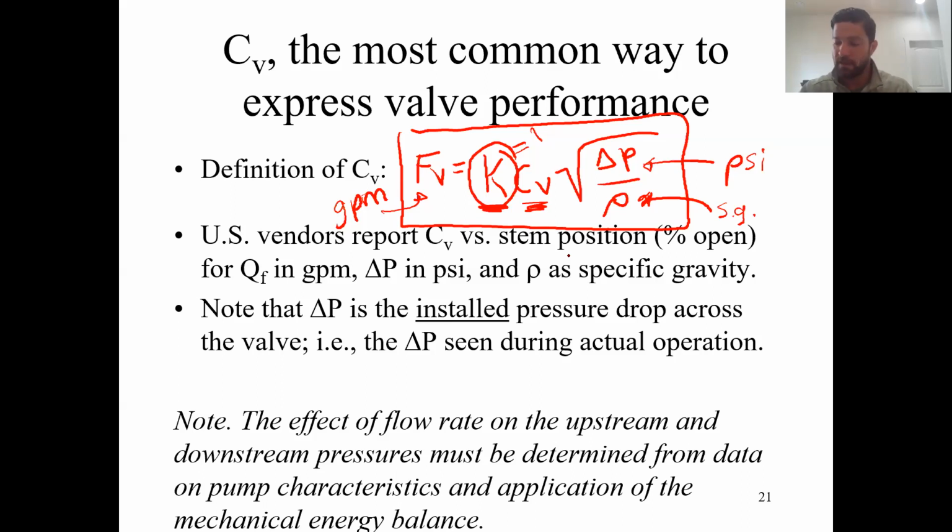All right, before we go too far, I'm going to discuss what this means for both linear and equal percentage valves. I don't have a lot of room to write, so I'm going to try to do my best. So for a linear valve, CV is a function of X. Here CV is the valve coefficient, and X is the valve position. Valve position can nominally go from 0% open to 100% open. So CV as a function of X equals CV max, which is the maximum value of the valve coefficient when the valve is entirely open, times X divided by 100.